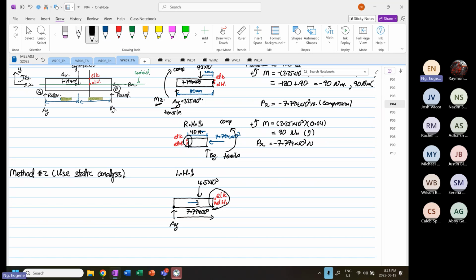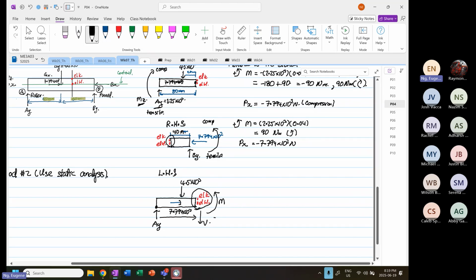So we are analyzing, and what is available is the material on the left-hand side. When you have material on the left-hand side, this is the positive shear or positive bending moment assumption. I just call this moment. Later on, the shear will be coming down in this direction, but we're not dealing with shear yet. Let's focus on moment because the moment will generate our normal stresses. So now if we take moment from this point,